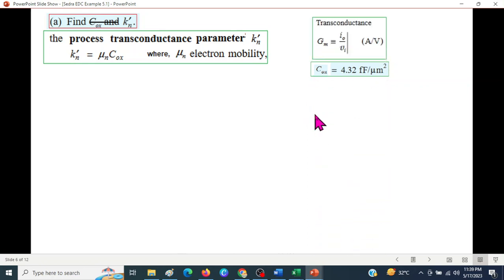and what is the transconductance? Just to give you an idea, just like the impedance is voltage over current, the transconductance is the current over voltage, but this is also admittance. But here the difference is that the current is output current and the voltage is input voltage, and therefore the parameter is known as transconductance.